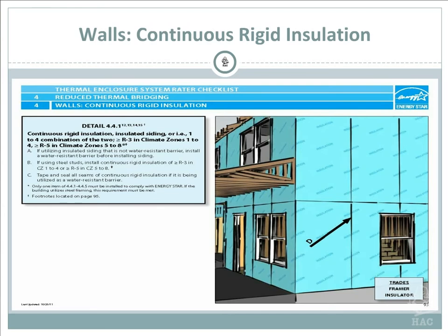Talk about continuous wall. These are pretty simple things. Everybody's pretty much doing this. You will need to install these. We talked about the R values, you need to have an R value of 21 or 19 in your area. You usually go with an R13 on the inside, R10 on the outside. So this is something that's pretty common.